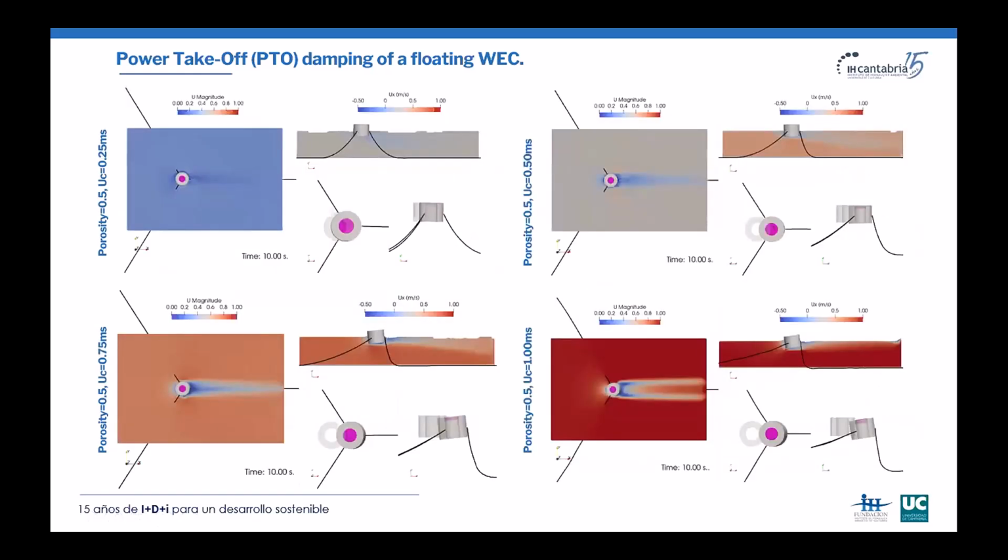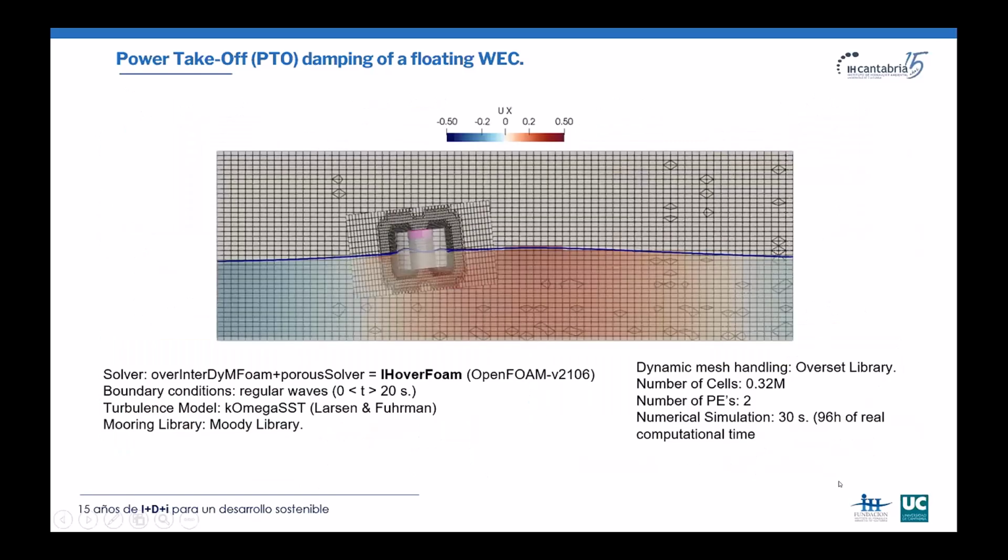If we go to the last time step, we have simulated just 10 seconds here, and more or less we have achieved a steady state. Then we can add the moorings here to see that they are working properly. And finally, when we have used it with currents, of course, then we can use it with some regular waves.